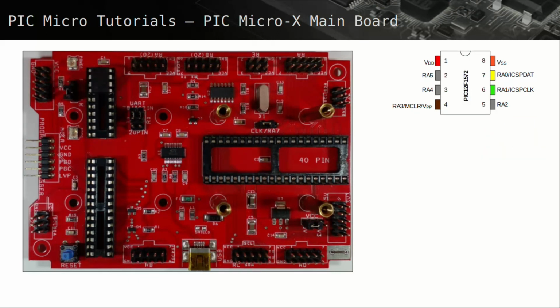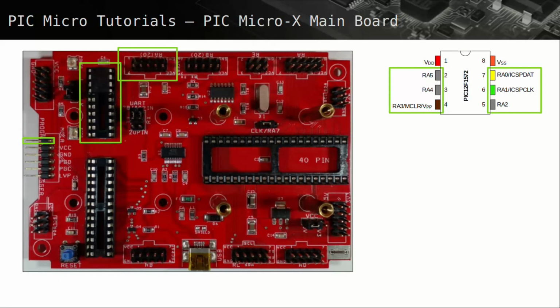The 8-pin PIC12F1572 is also installed in the 20-pin socket, as highlighted. Here, the actual device is installed to confirm both socket notch and device's notch are positioned above each other, ensuring the 8-pin device is correctly installed in the 20-pin socket. The PIC12F1572 8-pin device only has port A, pins RA0 to RA5, and port header pins RA20 are used.